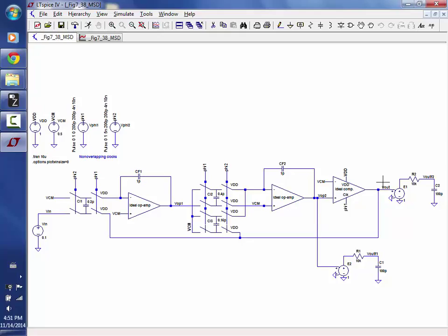But in reality, when you're doing the system level block diagrams, you have some swing here on average, and then you have some swing here. And so the swing, or the gain in that sense, with an ideal comparator is then finite, and we just calculate 0.25. Having said that, does that mean GC is 0.25? No, because from one clock cycle to the next, the gain is going to change.